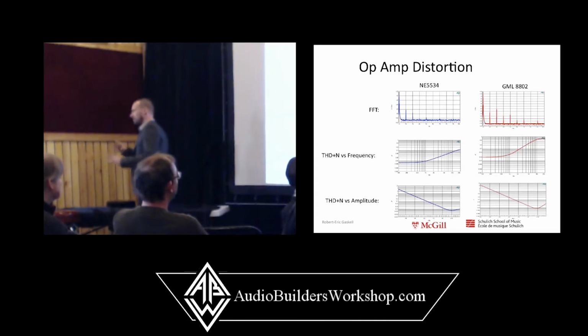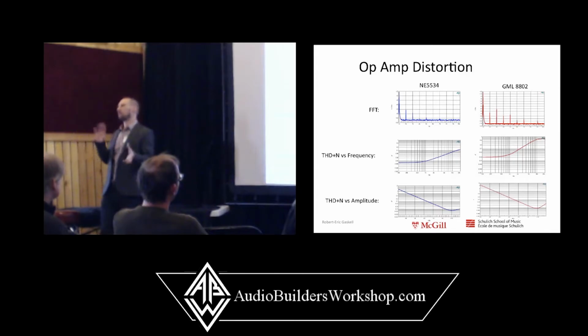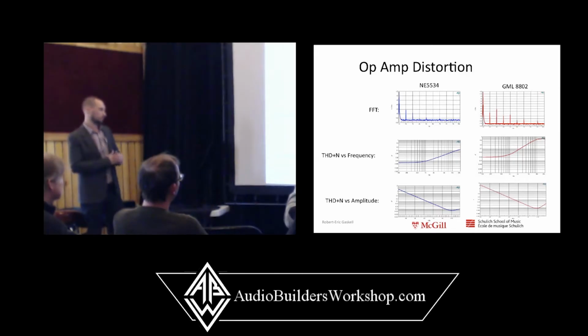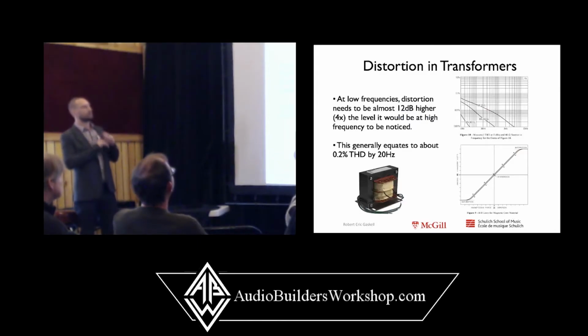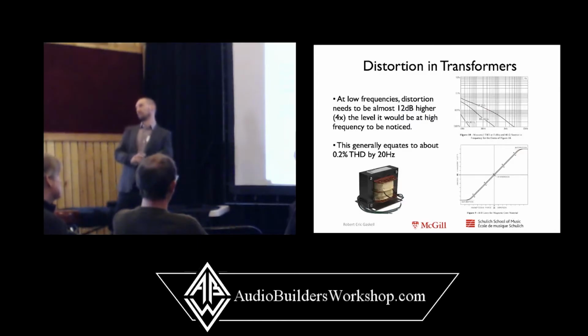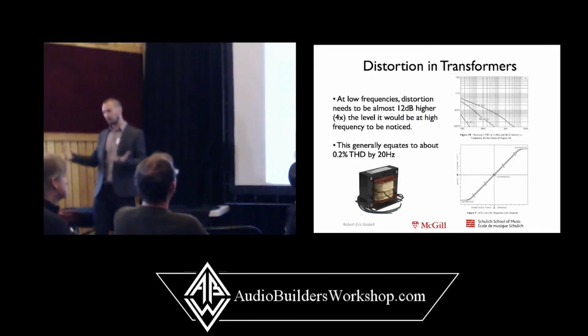So for both of them we see basically where in the gain range we start to see the distortion rise up above the noise floor. So it's in that area up there where we can expect that there's a potential for that distortion to be perceivable and affect the way that we hear the circuit. Okay.